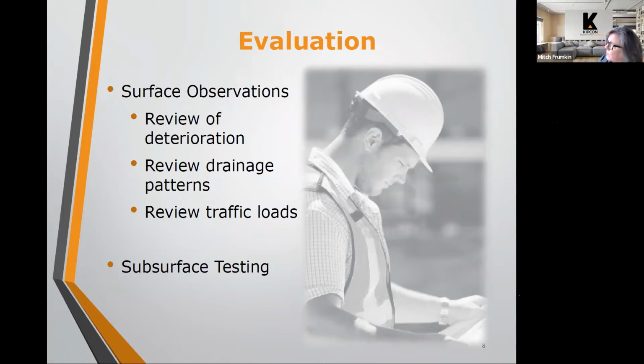I also mentioned part of our evaluation is subsurface testing. That always entails for us performing asphalt cores to see what the structure of that pavement is, because that becomes very important in the design of the pavement and ultimately the cost of the project. So asphalt coring is very important.